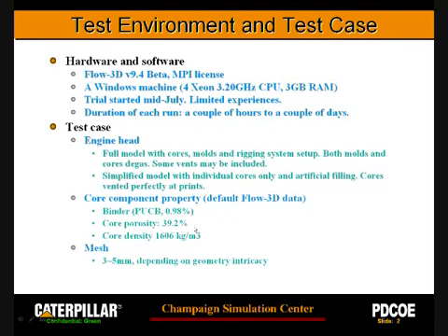like the binder content, the core porosity, and the density. The mesh size generally needs to be very fine. The reason is that core gas depends on the heat penetration inside the sand, and inside the sand you usually have a very steep thermal gradient. You have to use a finer mesh to resolve that temperature field. So that's, I think, a limitation so far in the software. That's why the runs usually take much longer.